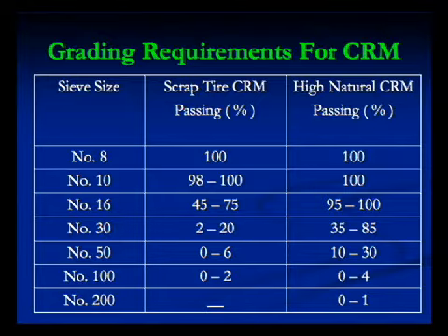When your contractor asks you for a sample, oftentimes mix designs are prepared 3 up to 6 months before actual production of the project. You submit that sample to the design engineers and the agency, and the mix design is designed based on the sample you provided 6 months ago.